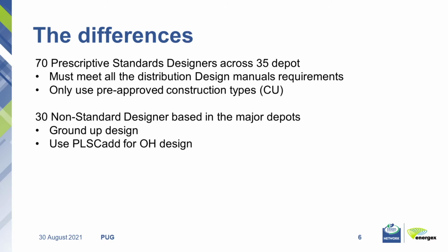Just a bit of background on our 2 design streams. Our prescriptive standard designers pretty much only do designs that meet our distribution design manual requirements. All the structures that they use, the pole tops, the poles, pretty much everything is a pre-approved construction type, and their role is to put it together in building block type scenarios. Our second group are our non-standard designers. They're our engineers. They design from the ground up. Pretty much all their overhead design is done in PLS-CAD.